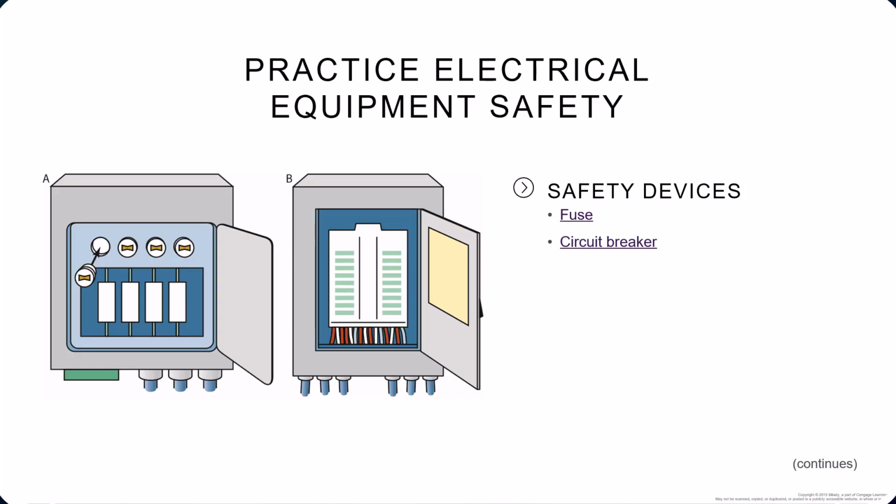A circuit breaker is a switch that automatically interrupts or shuts off when there is a first indication of an overload in the electric circuit. These are more common now since they've replaced fuses, and they don't require replacement and can simply be reset by switching the breaker right back on. If a circuit breaker does shut off, you need to disconnect any of the appliances that were connected to that particular breaker and check all the connections and installations before resetting it.